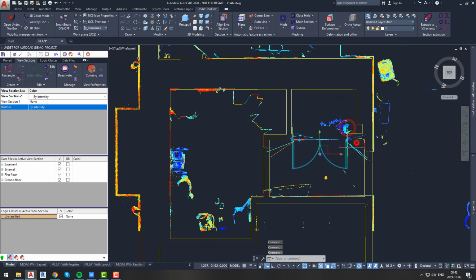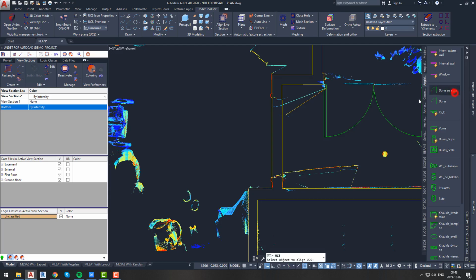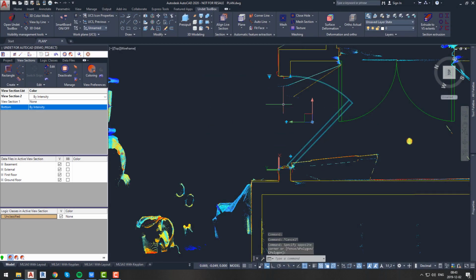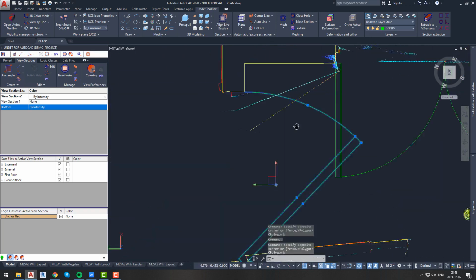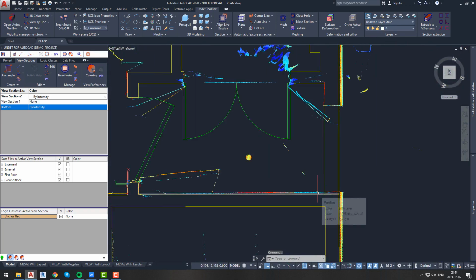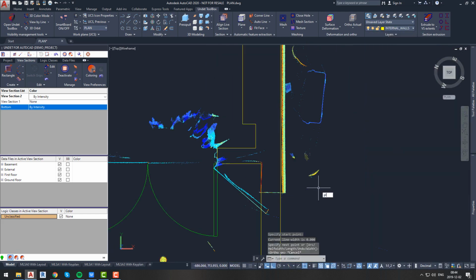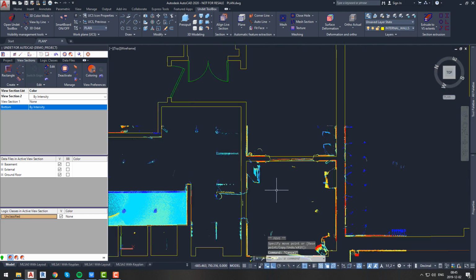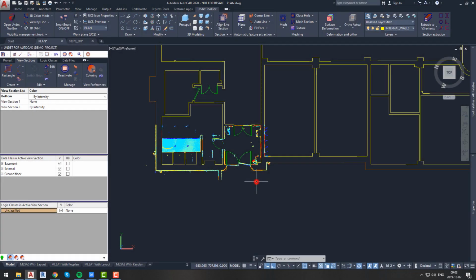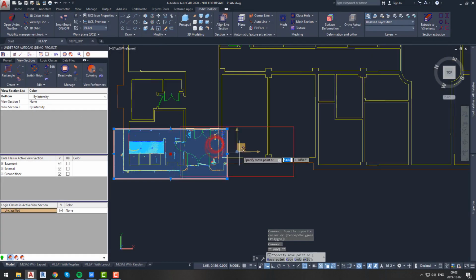As you can see, our dynamic blocks can be adjusted very easily. You can always change the door type, switch sides and adjust size. Our advice is to be very careful and check every wall, if you do not want to miss any doors. Also, every separate room should have at least one entrance, so keep that in mind while working with doors. After adding all doors, we can move on and add windows.